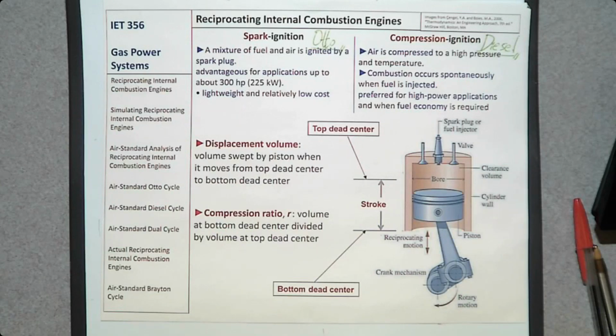But if you have a diesel engine, the combustion takes place at extremely high pressure because that's how we increase the efficiency. When combustion takes place at extremely high pressure, air is not just pure oxygen. Air has approximately 80% nitrogen and 20% oxygen. Nitrogen is usually considered an inert gas, which means that it's not going to react. But at extremely high pressure, it's going to react. So in a diesel engine, at this extremely high pressure, this nitrogen is going to react with oxygen. Then what we produce is air pollution.